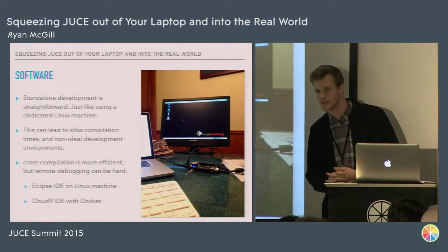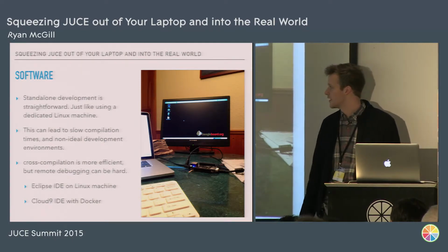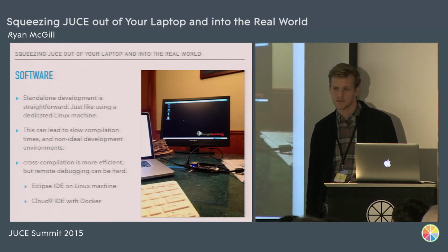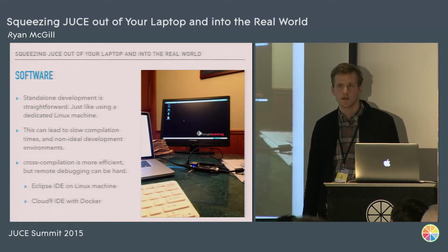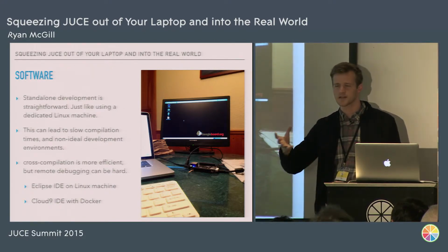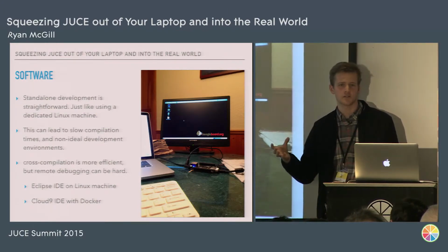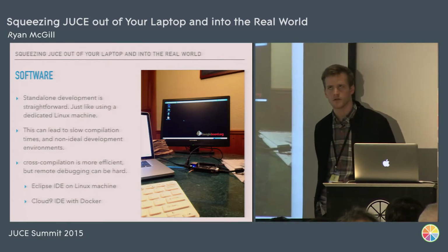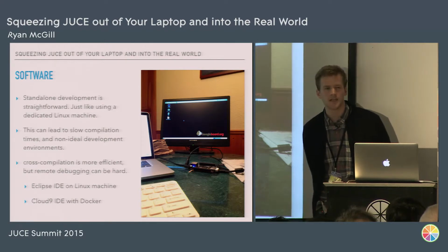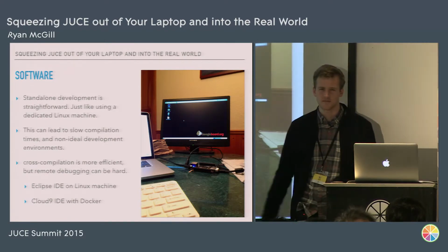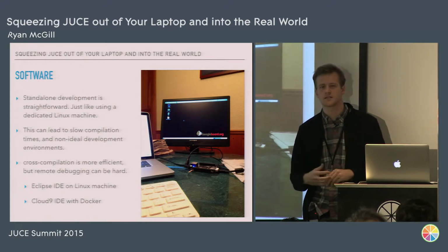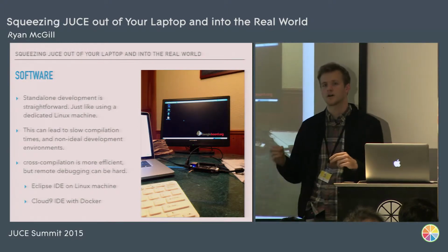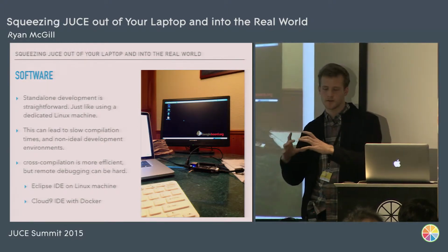Usually the operating system is some sort of lightweight version of Linux. I found the best luck using a version of Arch Linux to run on these machines because it had a little bit faster boot up time. And sometimes the way these operating systems handle floats can be an issue. The one on the BeagleBone that comes on that board is Angstrom Linux, I think is what they call it. And I think they do soft float mathematics, so all the float math is done virtually as opposed to hard floats, where all of the float math is done with a hardware chip.